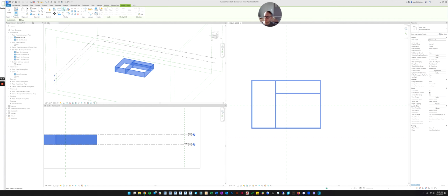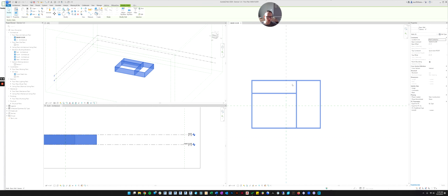and there's a little option here that says copy. I'm going to uncheck that because I don't want it to copy it. So I already selected what I want to mirror, and now I need to tell it what axis to mirror it over. So if I click this, it'll flip the whole house. And then if I do the command again, and if I pick this axis, it'll flip it that way.